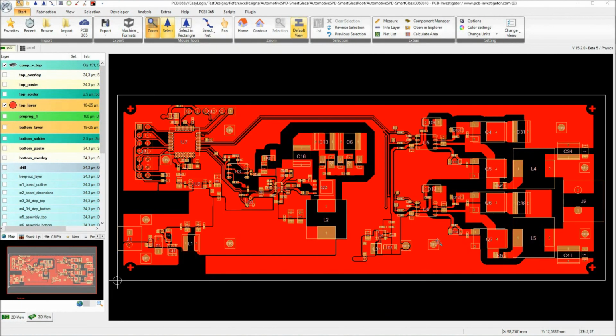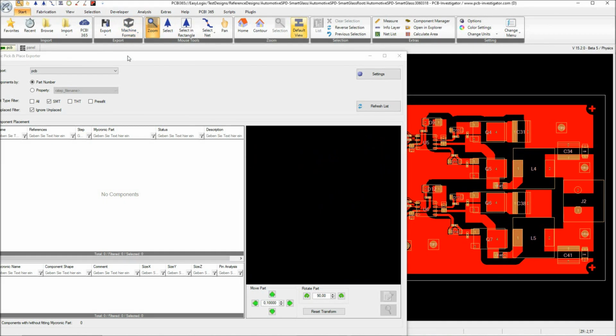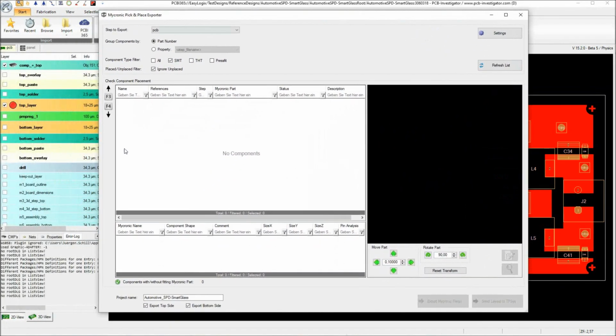Welcome everybody to this new PCB Investigator video tutorial where I want to show you the brand new Mycronic Pick&Place export functionality, which is included in the Production Control edition of PCB Investigator. We have a demo design here with two layers and around 150 components. A few of them are SMD, a few of them are through-hole components, and we also have a few test points there. And I'm going to start with the Mycronic Pick&Place export in the machine format button here.